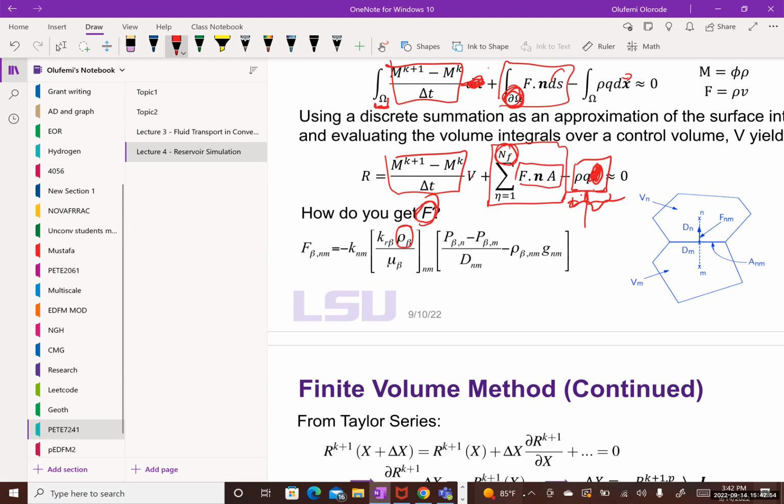You don't have to. Yes, for gas, you don't have to. Actually, when I write my codes, I don't. Just implement density. Let the code calculate density. You don't have to replace the equation with the expression for it. That's what I will do. That's what we do in numerical simulation.